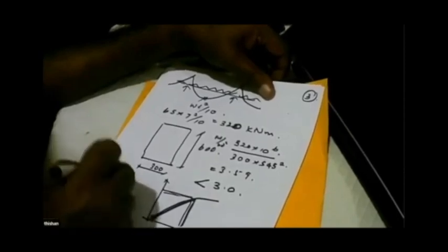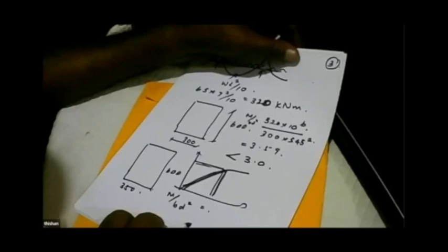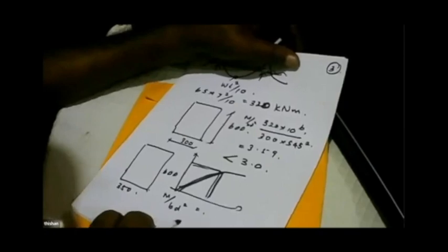So what I do is, now I'll select 350. Now what will happen if I select 350, by 600? So what is this M over b d squared? You multiply it by 300 and divide by 350. You get 3.2. Yeah, 3.2. So that's good.